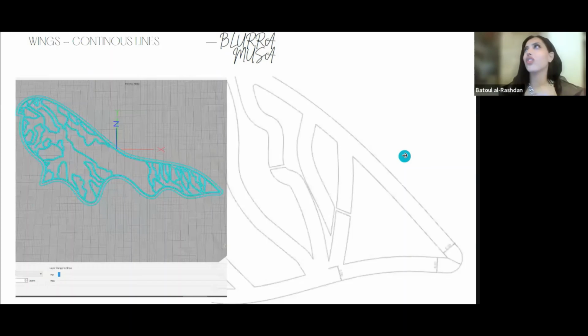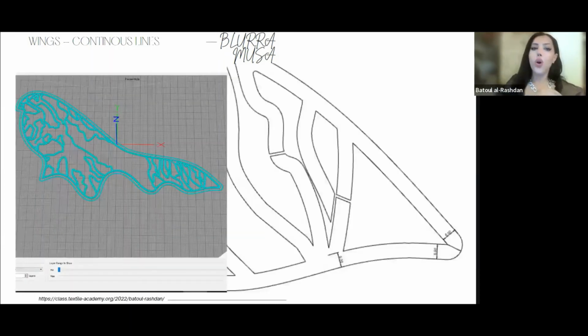The thing is, when you're a digital fabricator and you've been in this domain for quite some time, some years, you start designing for the machine and you know how the machine works. So I know the extruder would go one round, so I make the wing go maybe one round or a double round. I designed the width based on the printer and its extruder, so it goes once and doesn't start filling up between the lines. This technique is called the spiralized technique, and I managed to master it throughout the years by experimenting with it.